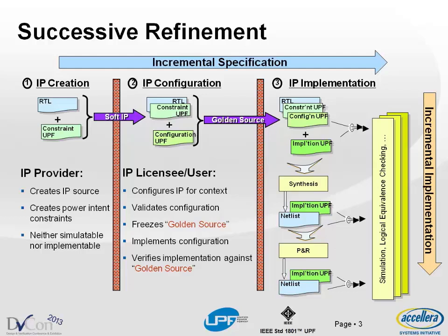For example, which library cell to use, exactly which is the power and ground net you want to hook up to your power intent. During this stage there will be changes, but you also want to make sure you keep the original golden power intent so that you can implement to what you have already verified. That's a very important thing to remember from the user perspective to design a flow or methodology using the UPF-based low-power design flow. And we call this incremental implementation of the power spec.